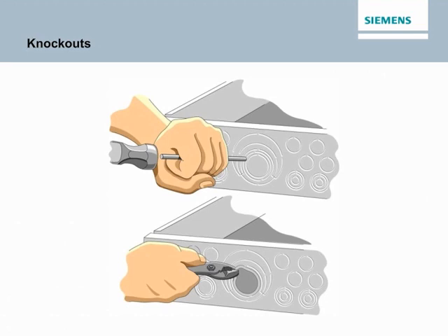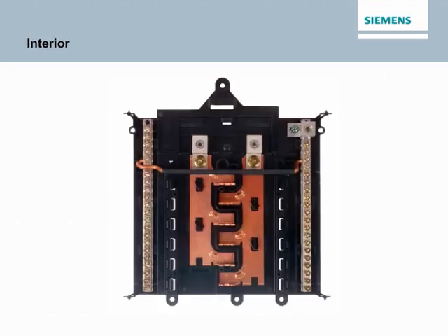If a larger opening is required, remove each additional ring one at a time by prying with a screwdriver and bending back and forth with pliers as shown in the following figure. The load center interior mounts inside the enclosure and includes bus bars and related hardware.